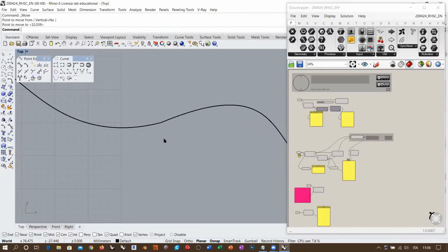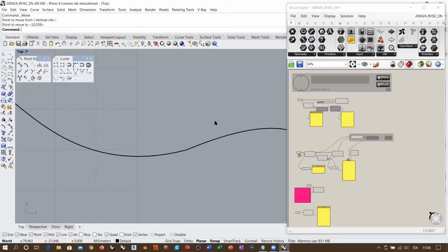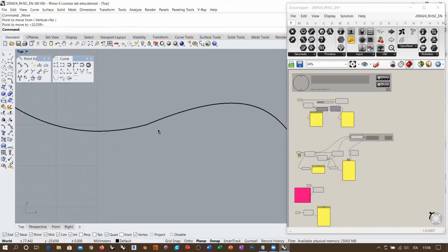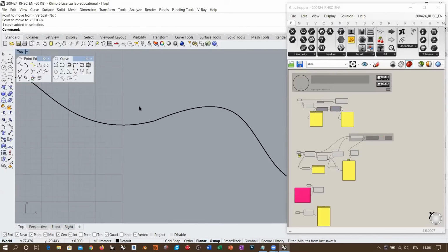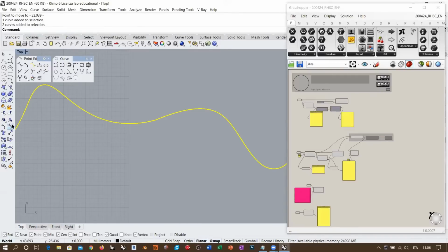And in order to do this, you see that things look pretty good already, but they are not that good, because if you go closer, you see that there is some kind of barely visible vertex happening. How can we adjust this? Well, in this case, I can simply turn on the control points of these two lines.